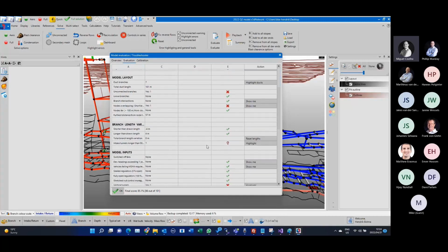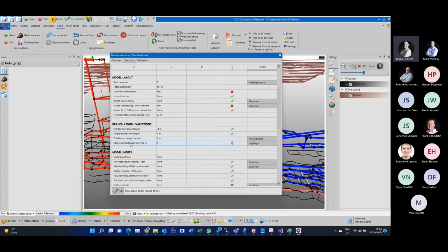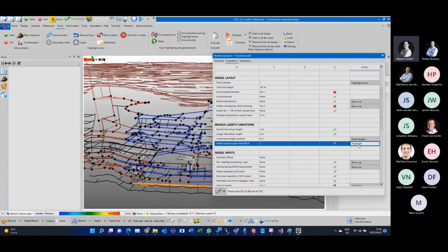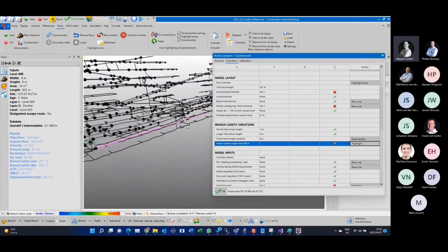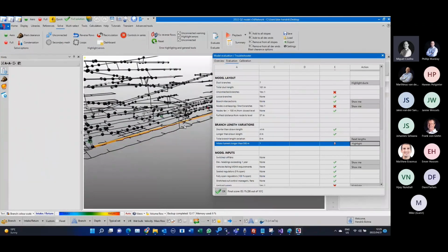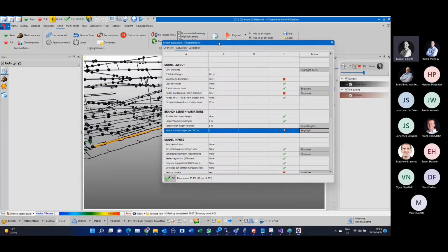First one is for long intake tunnels. A single long tunnel can have an impact on the heat transfer, since it will imply that the age of excavation in said tunnel is uniform, which is rather unlikely. For instance, a tunnel of 800 meters will not be the same age at the beginning and at the end. If the tunnel, however, is quite old, let's say more than 5 years, this effect is rather insignificant and you don't have to worry too much about splitting it into shorter sections.